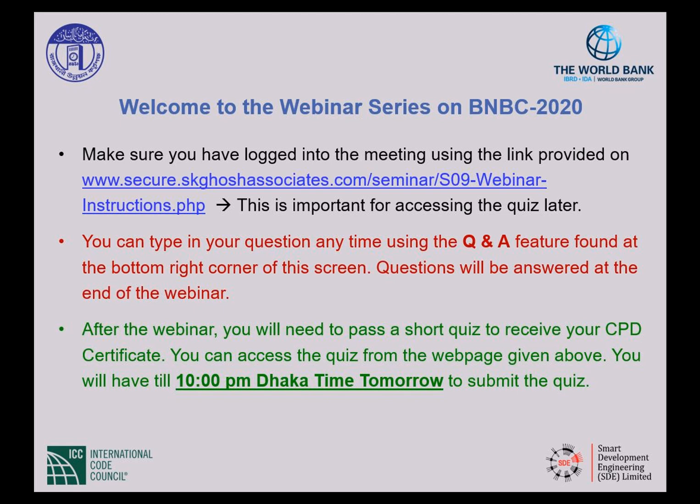Next question is, interstory drift is less or equal to 0.005 H. Is it correct to say? Because when we divide deflection by story height, that is called drift. Why is delta not called deflection instead of drift? I'm sorry, it is probably you are right, but the language in the code in BNBC is verbatim to the language of ACI 7. And yeah, in ACI 7, the language is like this.